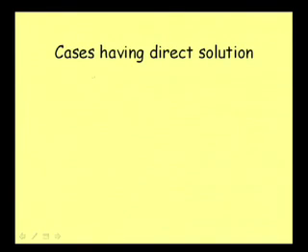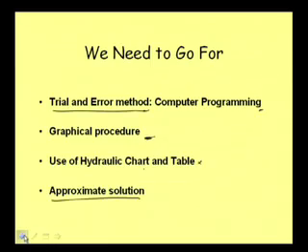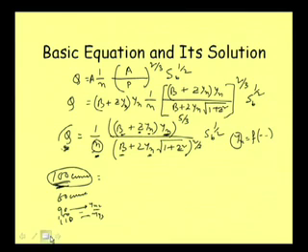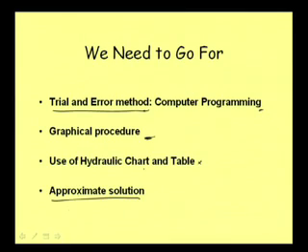Well, as we could write the formula, just let me start from this one, that is Q is equal to 1 by n, then (b plus z yn) into yn.